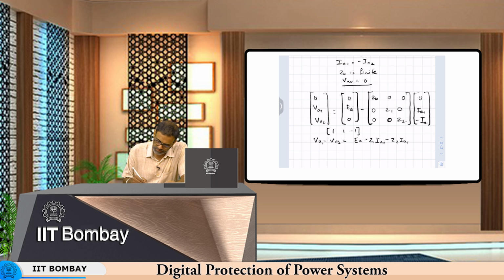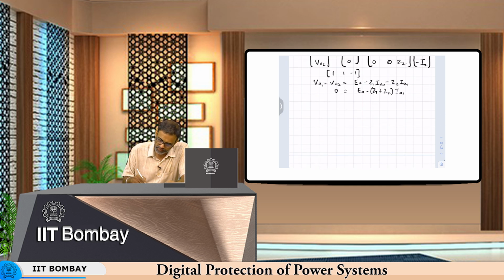Since this is equal to 0, we have 0 equal to EA minus Z1 plus Z2 into IA1. So, we have IA1 equal to EA upon Z1 plus Z2.